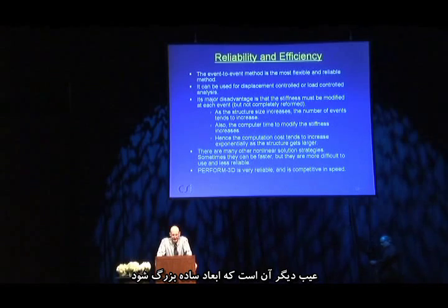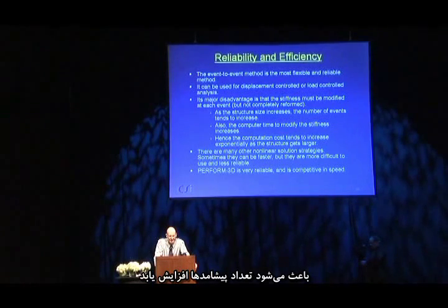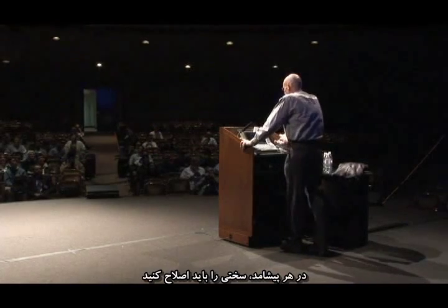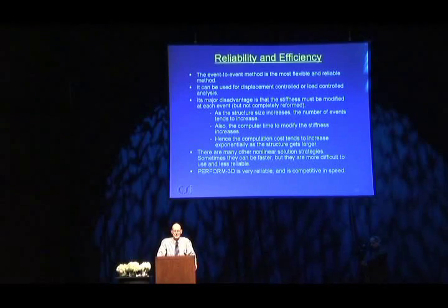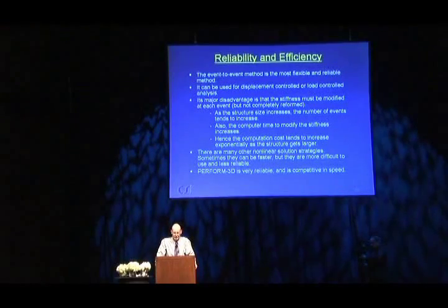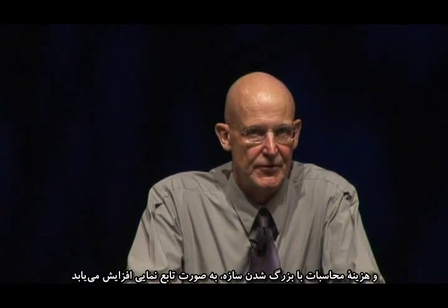The disadvantage, though, is as the structure size increases, a couple of things happen. The number of events tends to increase. It's just a bigger structure. There are more events that can occur. And at each event, you have to modify the stiffness, so the computer time to modify the stiffness increases for each event. So you have more events, more time to modify the stiffness for each event, and the computation cost tends to increase exponentially as the structure gets larger. Nevertheless,